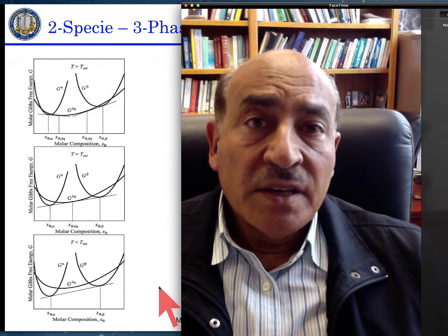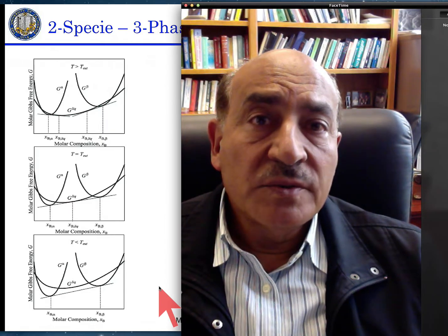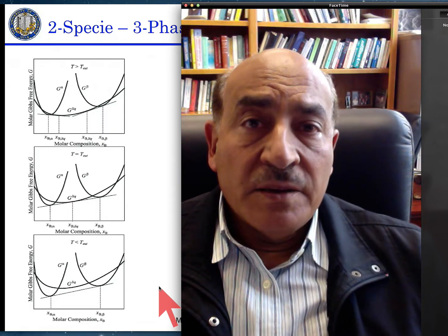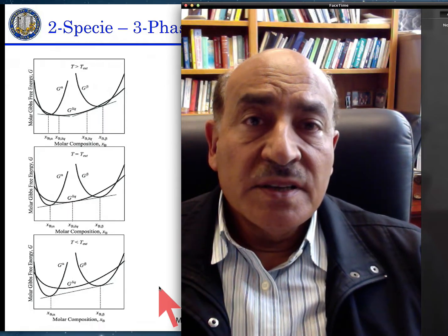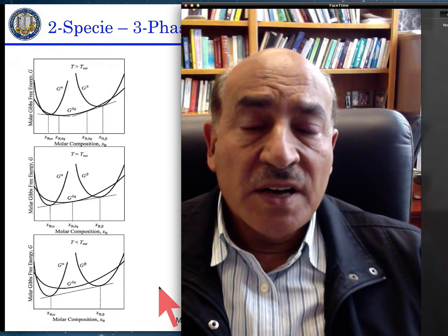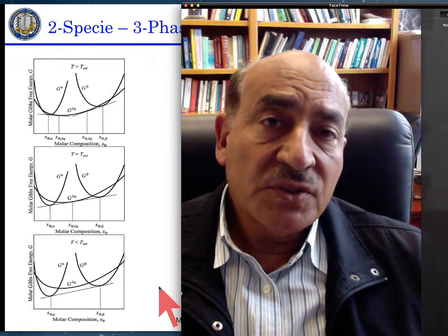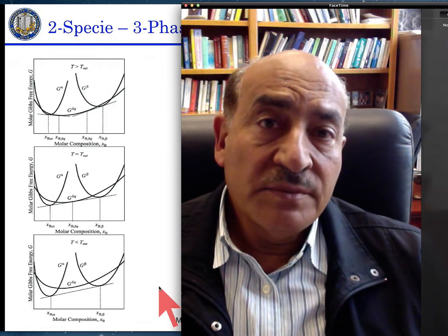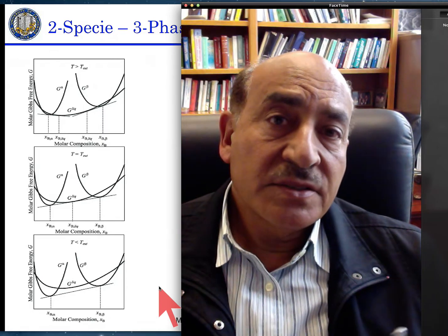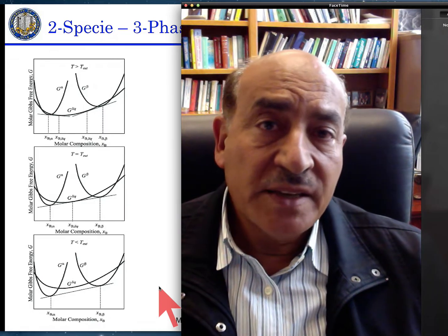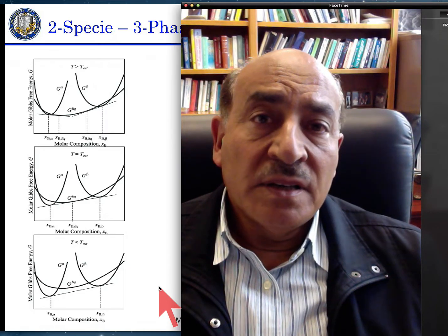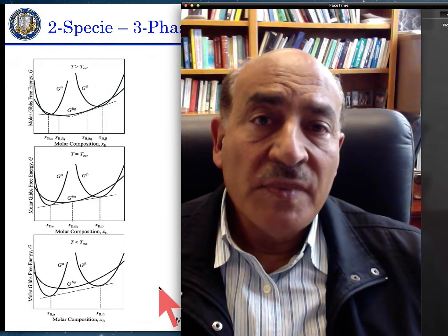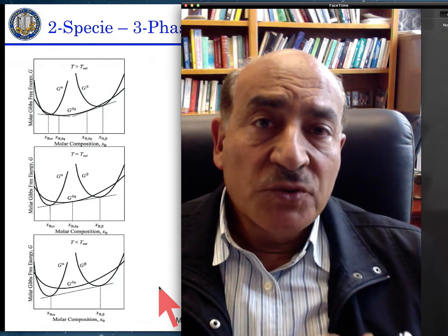When it's at high temperature, it will be a single liquid phase, but at lower temperatures, it may have a regime that has more gold in the copper, and a regime that has more copper in the gold, with corresponding structures. We can call one an alpha phase and the other a beta phase. So alpha and beta are two different spatial structures of the copper-gold alloy. So we need to study the equilibrium of this alloy.